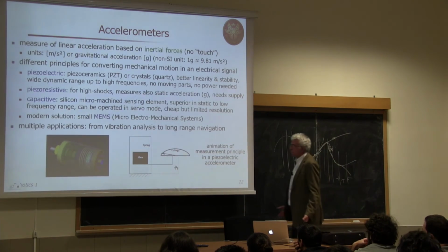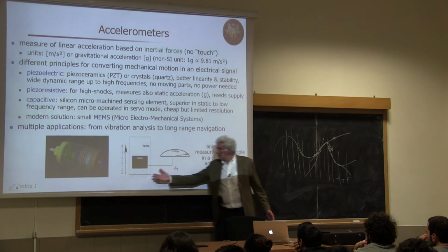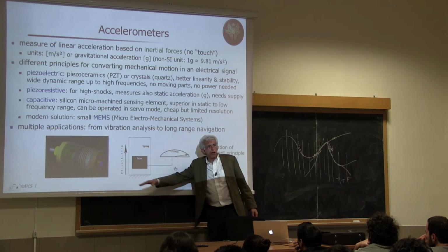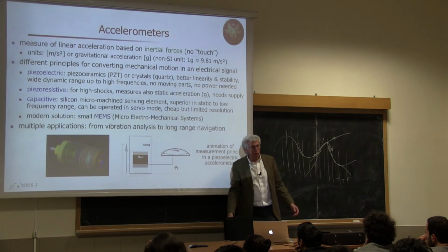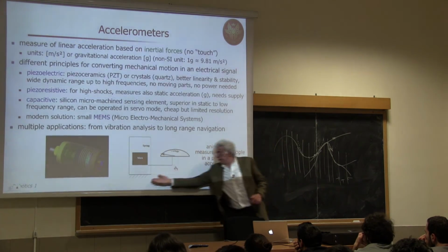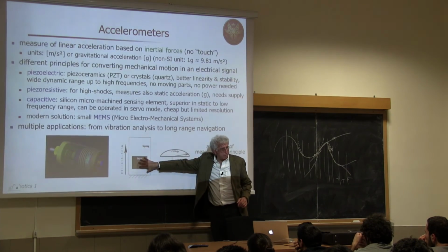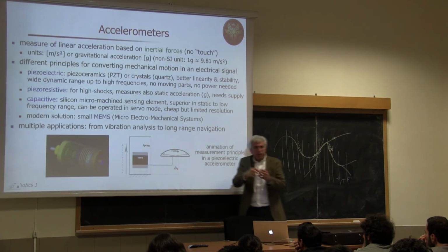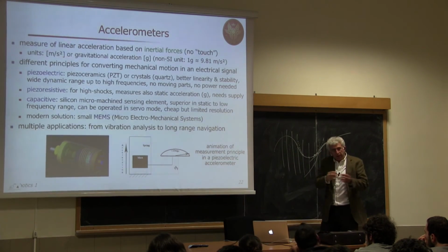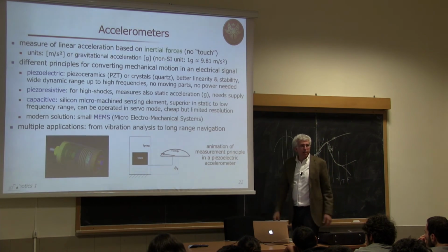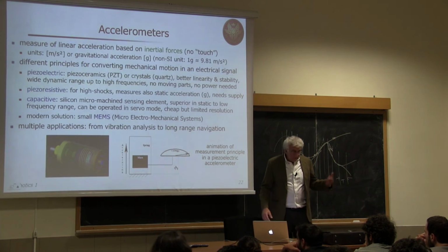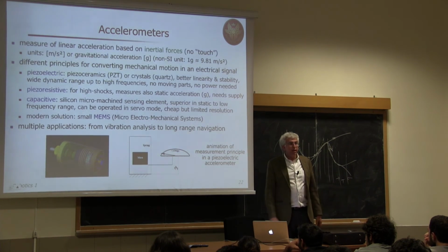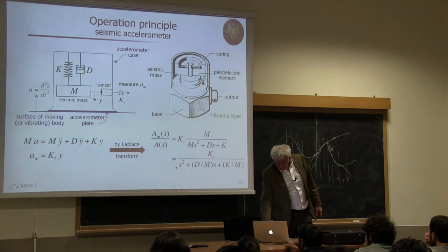Very simple idea. You don't have contact. This is the accelerometer that you mount, for instance, on one link of the robot. When the robot is moving, this base is accelerating, and you have a measurement in this direction. If you have a 3-axial accelerometer, inside the device itself you have three devices like this, and possibly they should not be coupled so that you can measure independent components separately.